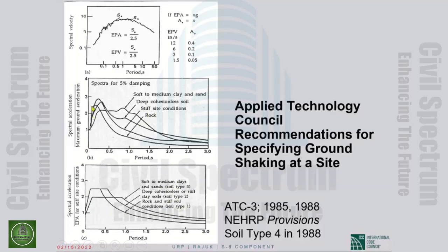And for design purposes, you see they have changed the shapes somewhat because they thought that the altered shapes are more suitable for design. And very importantly, they have normalized the spectral acceleration not with respect to peak ground acceleration, but effective peak acceleration for stiff site conditions.